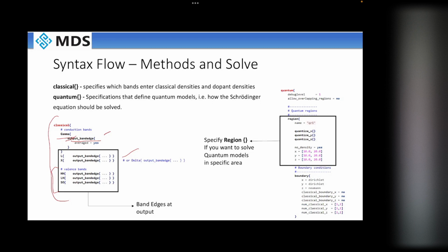If you want to see the intrinsic density, that statement you need to use. So accordingly, you need to provide the output statement, so that it will be included when you simulate your device, and then you can visualize it in the output.